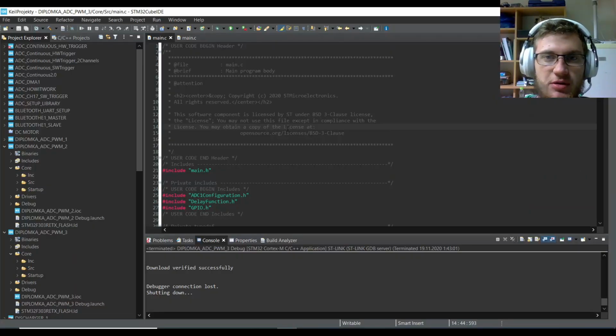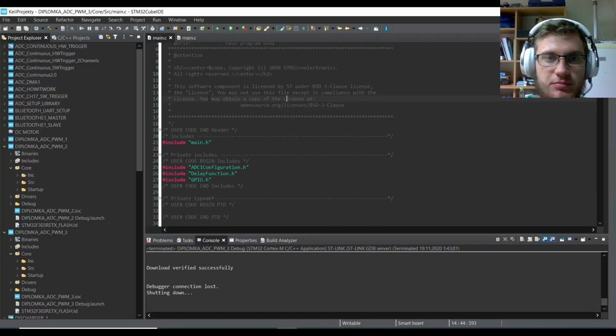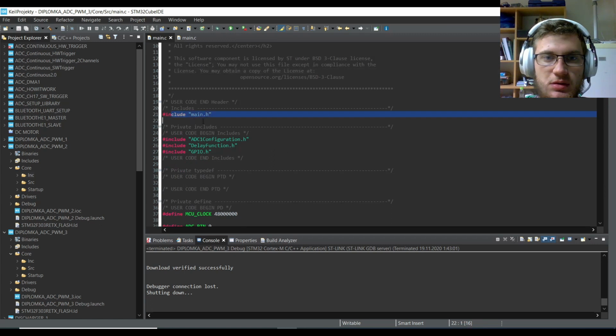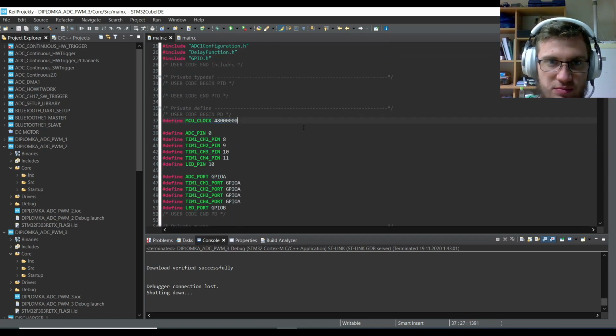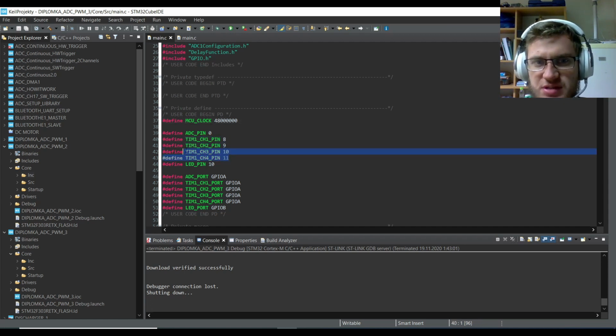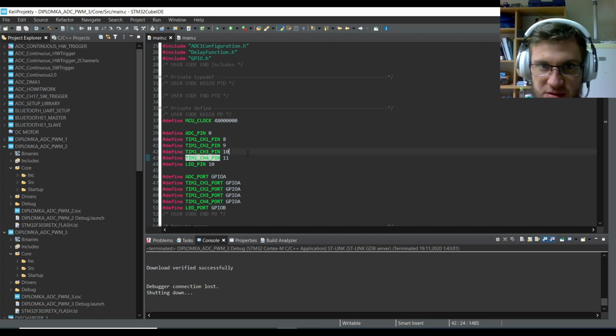Let's go into our second code. Again, this is the same. But you see that I'm actually using 4 pins for one timer, but I want to do the output just from 2 of them. You actually do not have to set the GPIOs for those 2 pins, but just to make it more visible, I will do it.